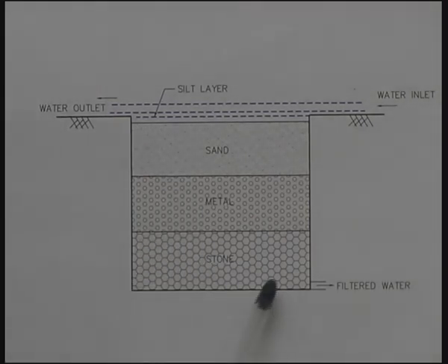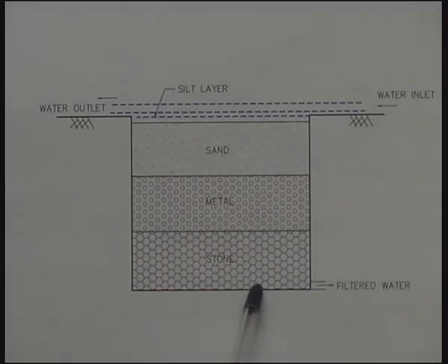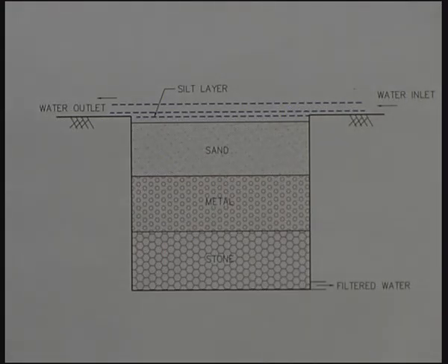If supposing we want to collect that water and then store it for future use, domestic use or gardening, then it is required to take it through a filter like this and collect the filtered water. But if it is intended for recharge in the water table, such a filter is not required. There is one problem with a filter of this type with regard to the rates of infiltration.